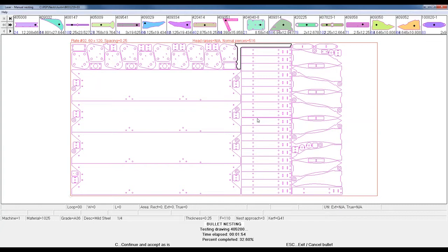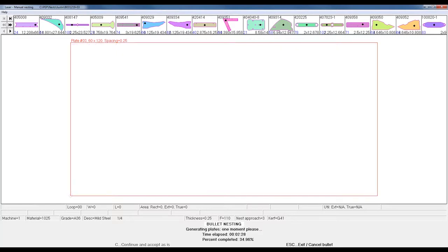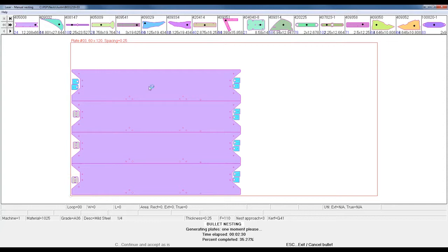That's going to help with stability of the skeleton and with heat management, so you'll have some meat in the skeleton, and it won't wobble around when you try to remove it. And speaking of the skeleton, another thing we also offer is skeleton slicing, but we'll go over that a little bit later. That would just be cutting up the skeleton into easier to remove pieces for safety and also for some premium value on the scrap possibly. But there we go, sheet 2 is done.